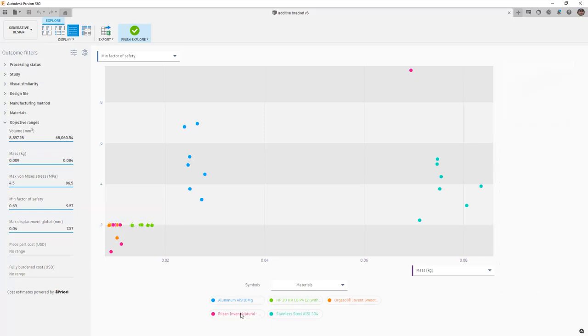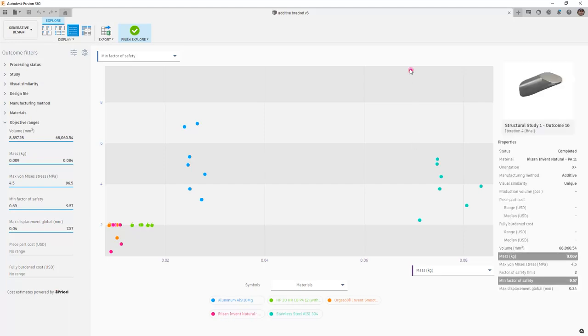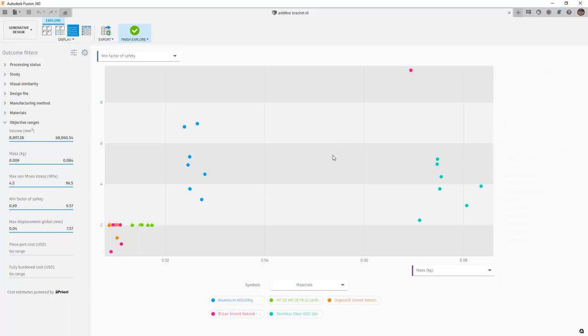For example, you can see that the real sand material is up here in the upper right, and this really did not produce very much at all. It only went through 4 iterations, and this is its final. It didn't meet the factor of safety limit. It's still at 9.57, which is well above what we need, but that's just where it completed its process. Now, there are other options down here in different orientations where we can see X minus, we can see the unrestricted method, but this one up here that was in X plus just did not produce good results.